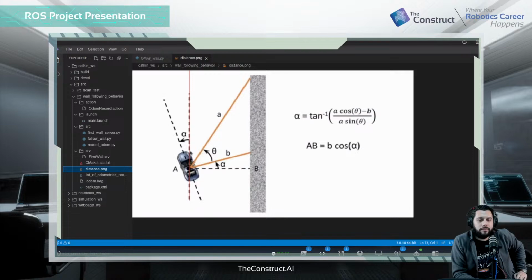So what I have done is that I have added L sine alpha. L is a completely arbitrary value I give to my code. By increasing L, I will be increasing the effect of alpha, and I am telling my robot, please respond more strictly to alpha. All right, I don't want my robot to have any alpha when it's walking.